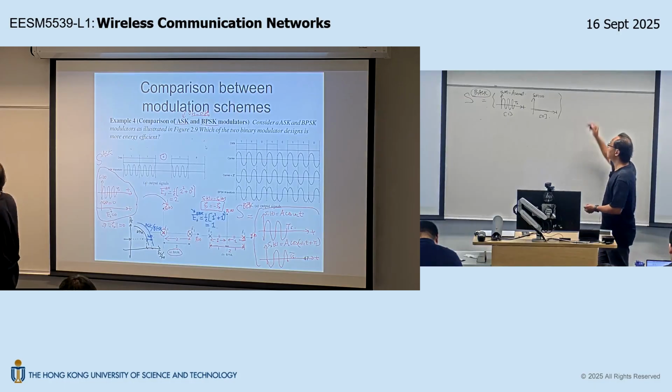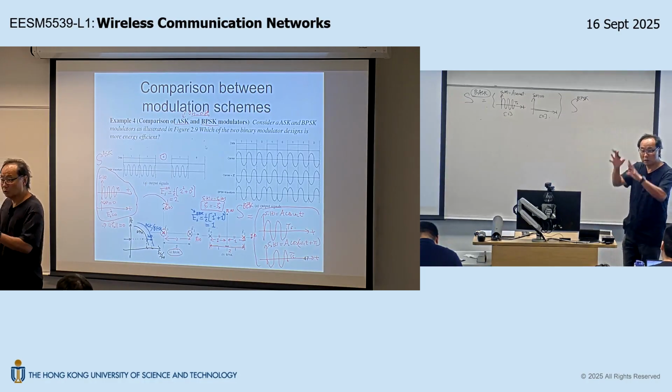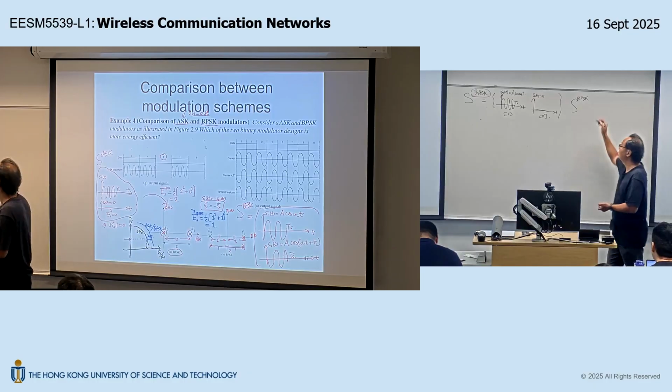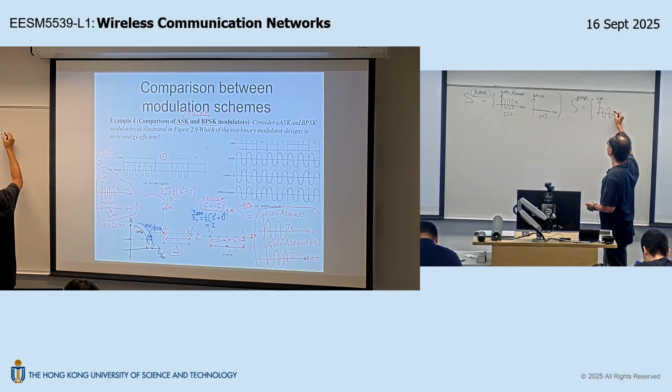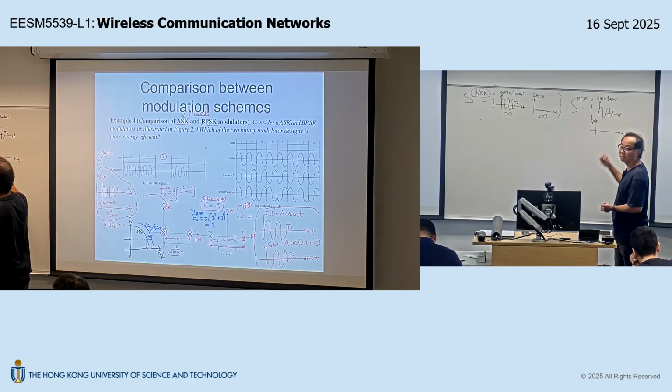Now another famous design is called BPSK, binary phase shift keying. So using our black box model, it is nothing but just another design, okay? And this second design is like this. My S1(t) is a sinusoidal burst given by A cosine omega ct. And my S2(t), my second member, is a 180-degree phase shift.